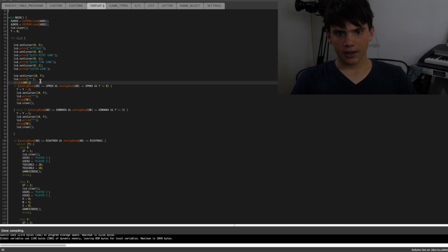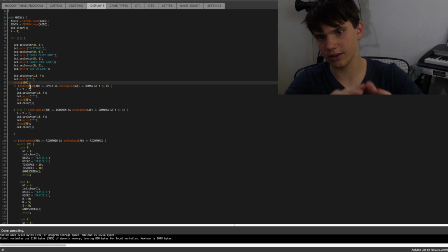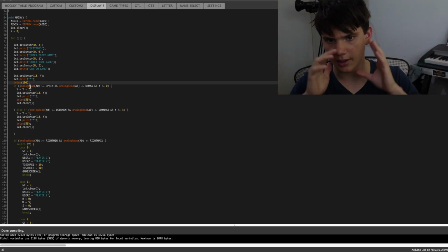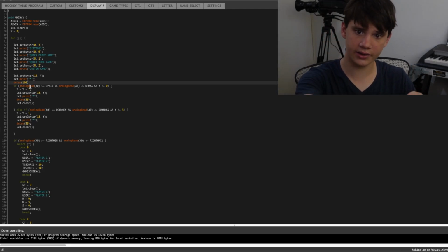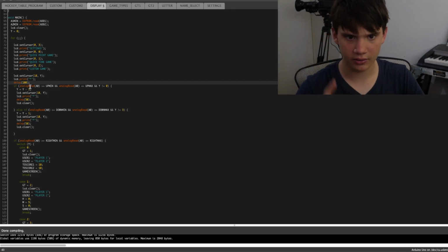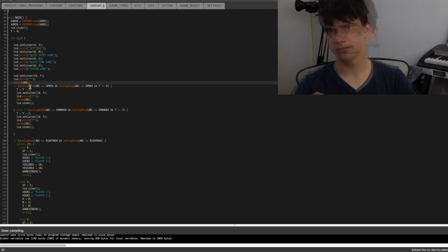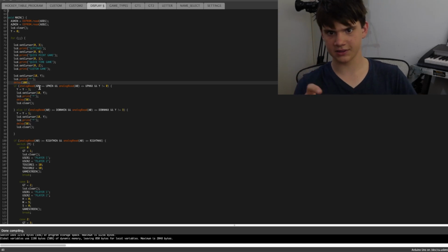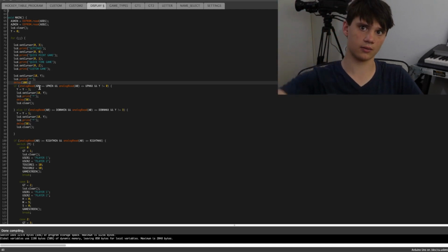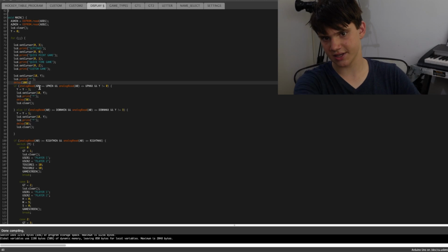And then we go ahead and if analogRead A0 is above or equal to up min, and so that's just basically reading the entire value of analog 0, which is up. So when you go up and y cannot be equal to 0, it's going to go ahead and go y equals y minus 1. So it actually moves the cursor up, but it can't move it up when it's at 0 because it'll go back down to below. So I've gone ahead and just implemented and then y is not equal to 0.